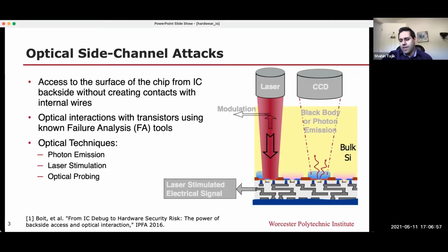You don't stimulate anything, but you usually have a camera, and from the backside of the chip, where you have only silicon, you can put your camera on and try to observe the photons which are emitted from the switching CMOS logic. These photons usually carry some useful information. At least they can show you, for example, where an IP core is located, when it becomes active.